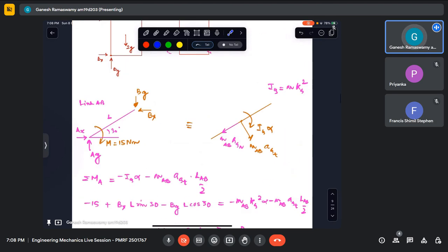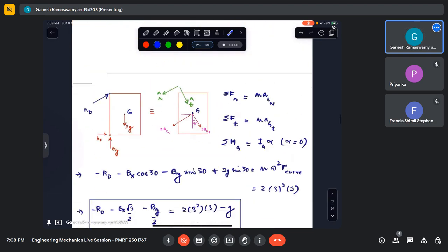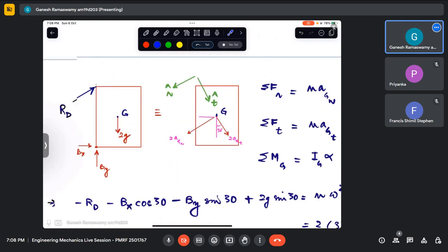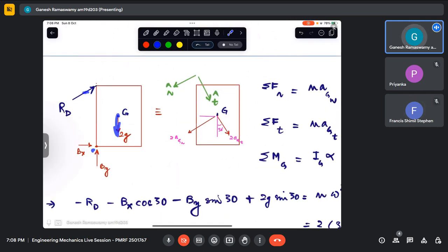We are doing this, right? Sigma M equaling 0. See, in this free body diagram, you are saying there is one additional moment. That is all you are saying. In addition to this weight and these reactions that are coming by the pin, if there is one additional moment, right hand side still remains same. It cannot rotate. It can at best undergo only curvilinear translation. So where will the effect of that moment go? That will get adjusted into these quantities. The magnitudes will mobilize themselves to counter that. By enforcing that equilibrium only, we are finding these, right?